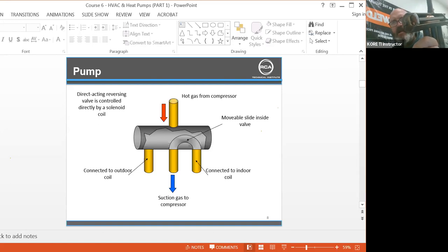So if you look right here, this is actually a neoprene washer. It's flexible plastic. This is why it is so important, when you're talking to your young techs, to keep this in a hot block, like the solder weld hot block back here, or cover it in a wet rag to protect this neoprene washer. Because when you burn this valve, it will still slide on the inside, but it will no longer work because you melted this seal. I don't know if you guys can see that.